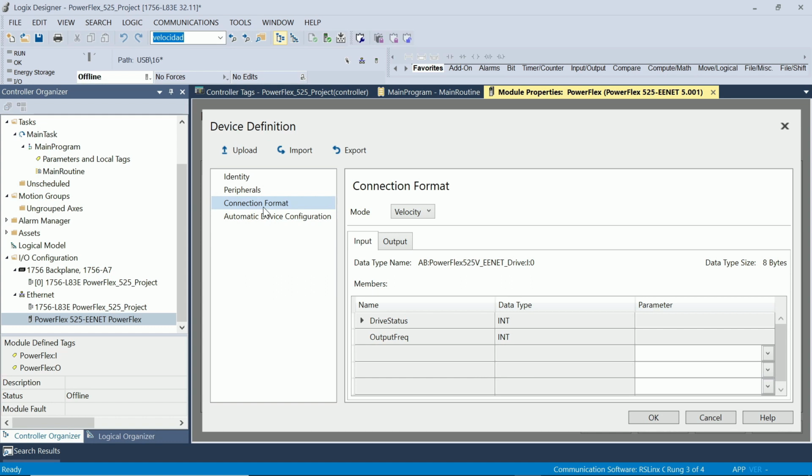So everything makes a lot of sense, and I'm telling you this because automatically our drive already ran its mapping, which is what they consider matches the drive, which is the drive status map drive, which are integrated by these booleans. That's why I told you about this. And then there's a new word, which is a double integer, remember, which is our output frequency.